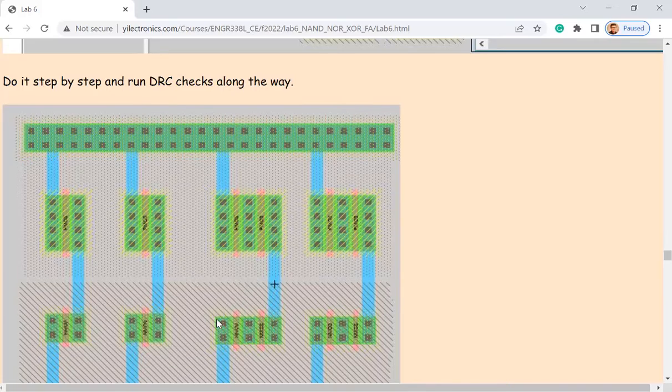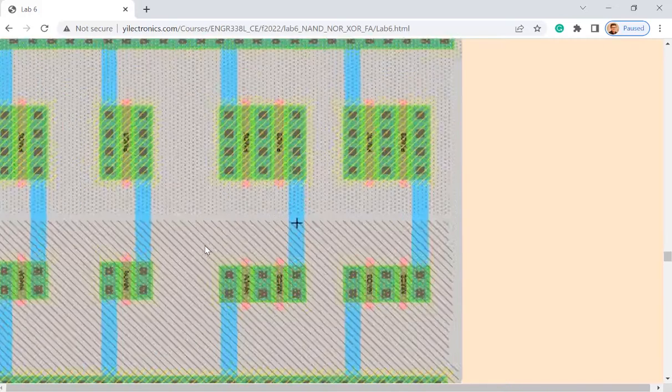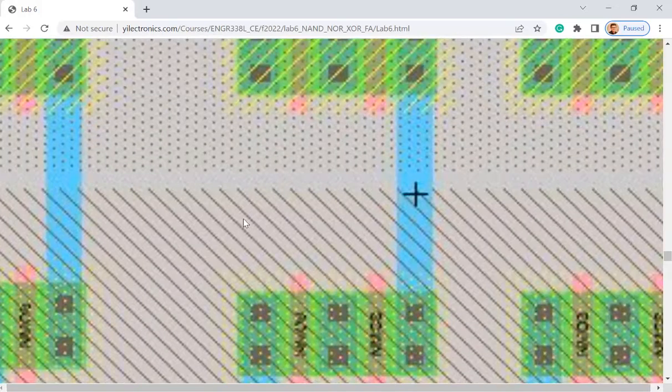Makes sense. Same for the NMOSes. See, NMOSes are in where? The slashes, right? It's very interesting because the NMOSes are directly in the P sub. You guys are saying NMOSes are being fabbed in the P well. Sometimes they are called P wells, but you don't really have a P well. It's just P sub. It's P type substrate. That's how they label it. Instead of just drawing nothing, they draw all the slashes like that as a P sub.